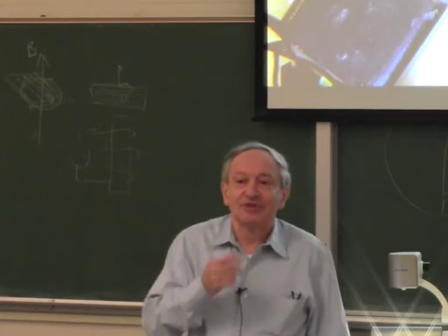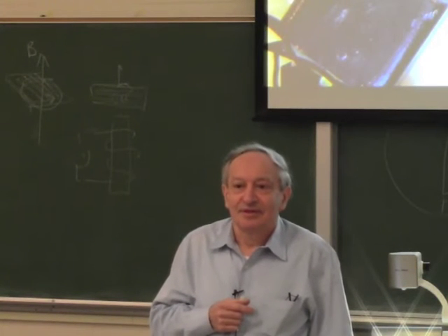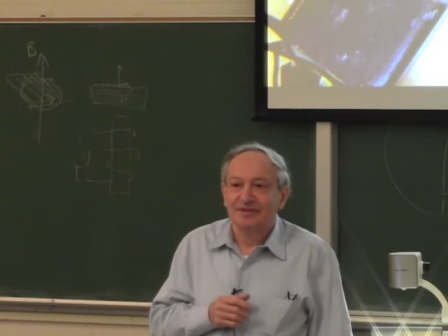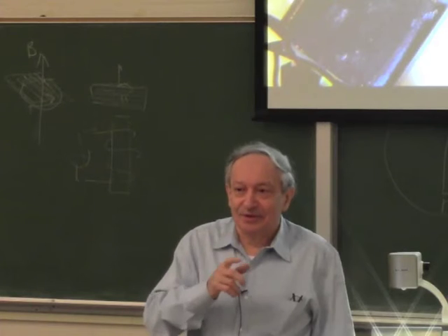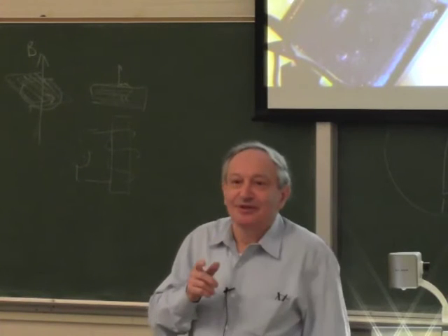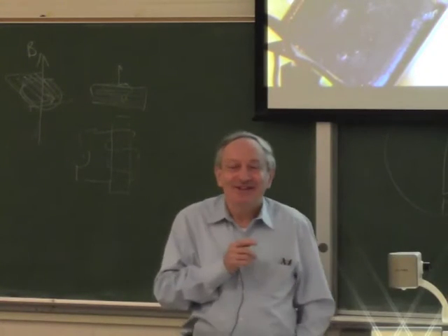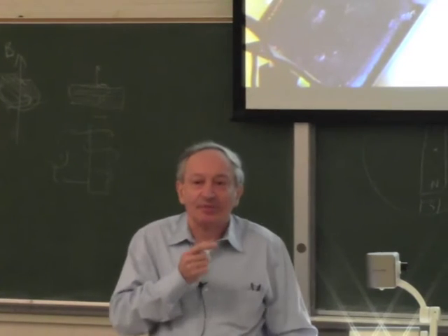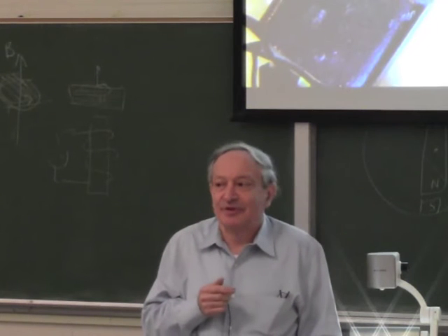What's the difference between these two fields? One is opposing the other. No, what about the phase of these fields? You have a 90 degree. So you do remember, you're just shy. Okay, good. That's reassuring. Okay, so why is the field coming out from the copper side 90 degrees behind the field which doesn't have copper?